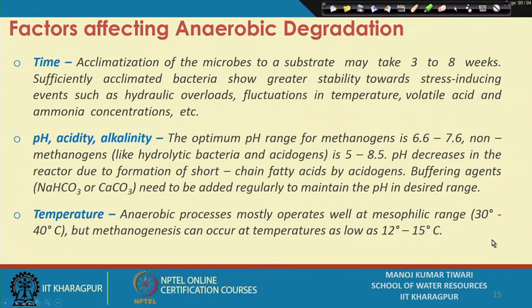Okay. To begin with, there are various factors that affect anaerobic degradation. The time, which is one of the important factors. As we were discussing earlier also, the acclimatization of the microbes with the substrate present in the system may take a significant amount of time. At times it even takes more than 2-3 months, but generally it is likely to take 3 to 8 weeks.